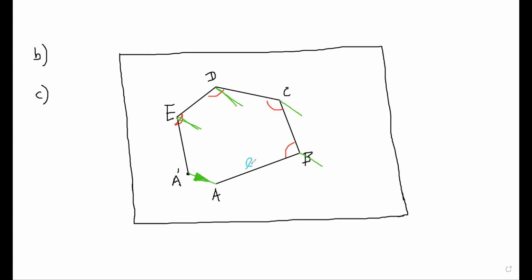Let's say this is L1, L2, L3, etc. Right? Then we draw a line and let's say this length is E. This misclose is E, the total. So we call this E the linear misclose.